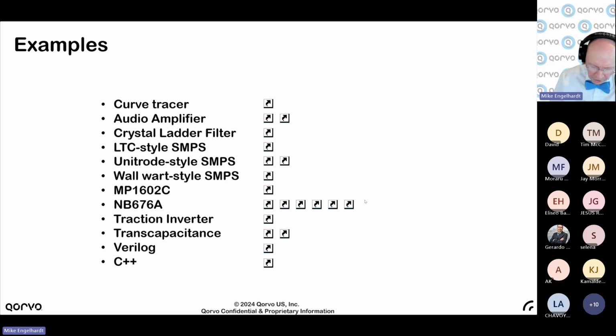If it does, then you're simulating an old circuit that isn't interesting anymore. If you're doing anything leading edge, you don't have models for what you're simulating. So what's important is to be able to import models easily. And just like you can drag and drop measured data into a waveform viewer, you can drag and drop models into a schematic, and then it'll make a symbol for that model, and you can simulate with it. And I will demo that in some detail later.